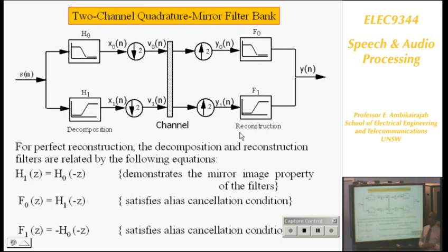So they used a technique called two-channel quadrature mirror filters. You know this technique, yeah? Where you have your signal, so 1,000 samples coming here, low pass filter them, you get 1,000 samples, subsample by 2, you get 500 samples. Then you upsample at the receiver, and then pass through two similar filters but with different phase, because the aliasing has to be cancelled out. This is plus here, sorry.